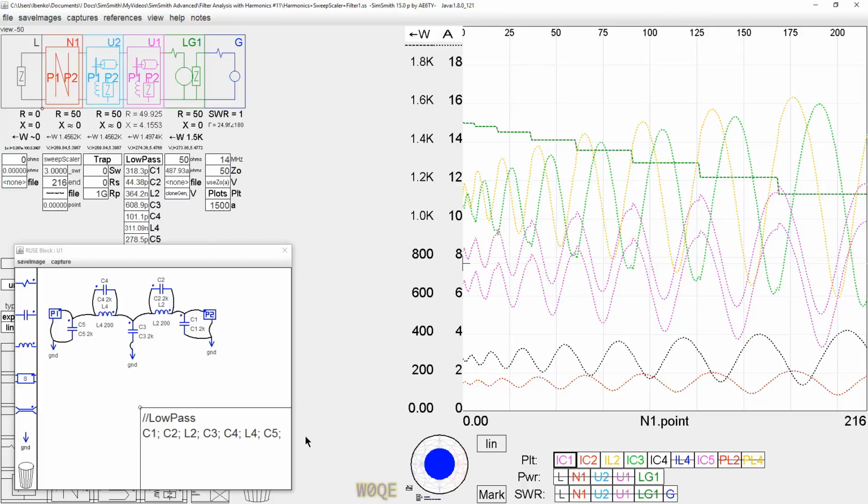It's kind of interesting. And it really doesn't matter whether they change or don't change. It is what it is. This is what you get if you put in a harmonic that's about 10.5 dB below the fundamental. If I wanted to size my inductor appropriately, and I wanted it to work all the way up to 3 to 1 SWR, I've got to find the biggest peak for my inductor current. The biggest peak for my inductor current is right there.